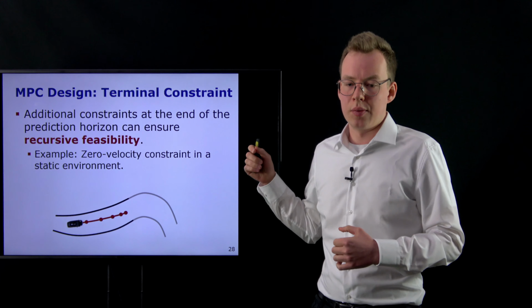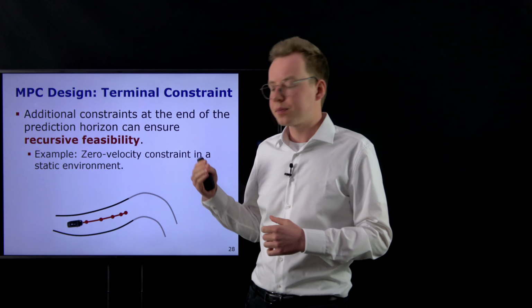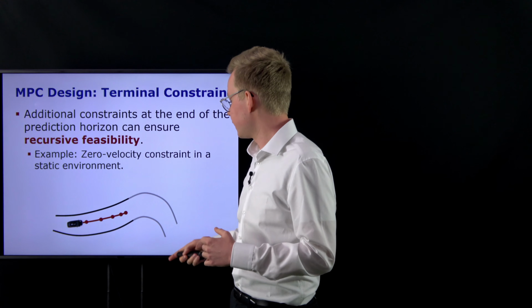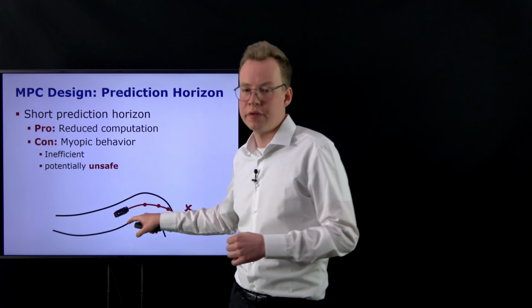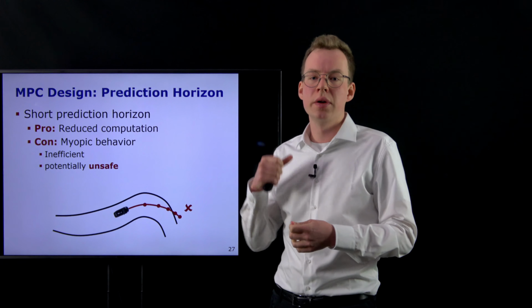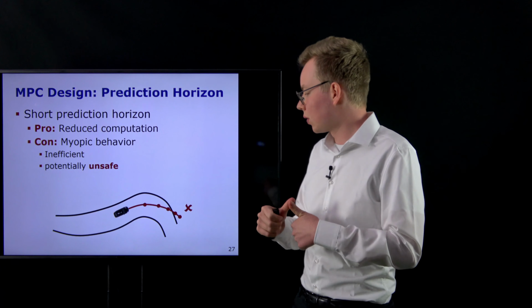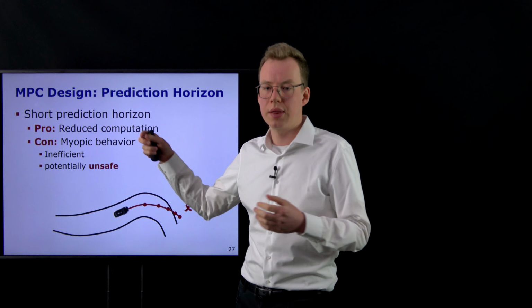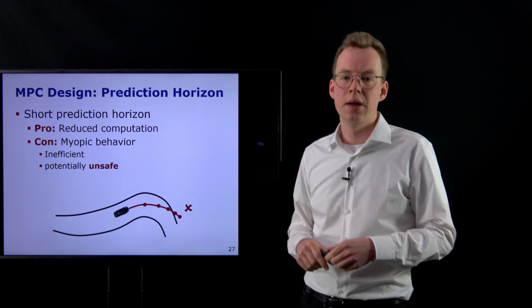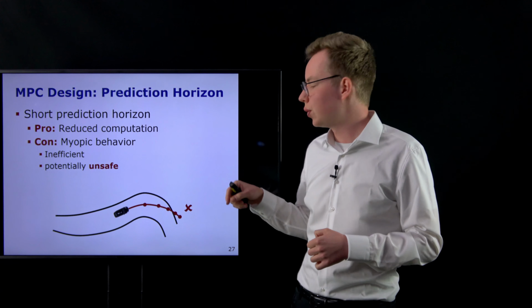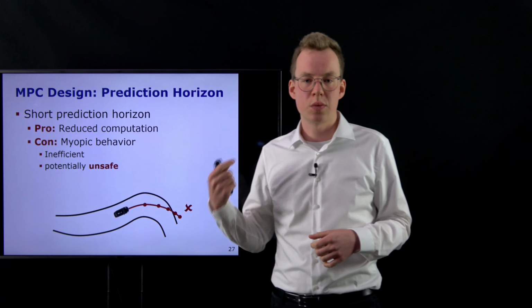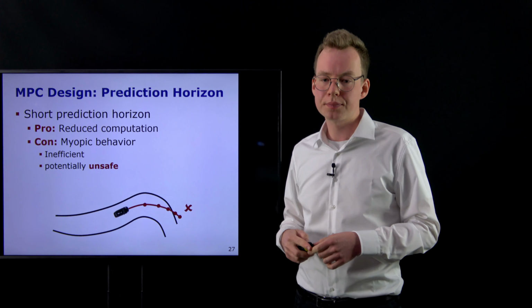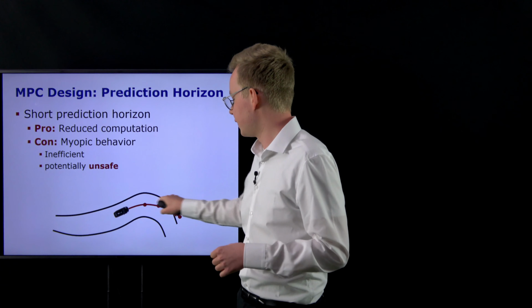So with feasibility, I mean that at this previous setting here, where we are not able to make the turn, the problem became infeasible in that there are no control inputs that we could apply here, in the allowed set of controls, that would keep our car within the track bounds because we were already so fast. So this problem became infeasible.